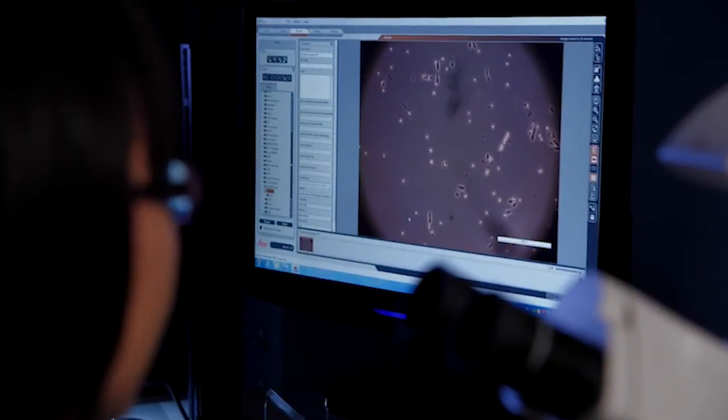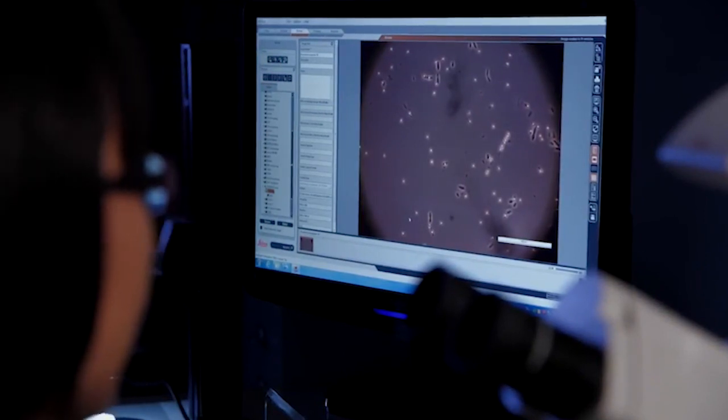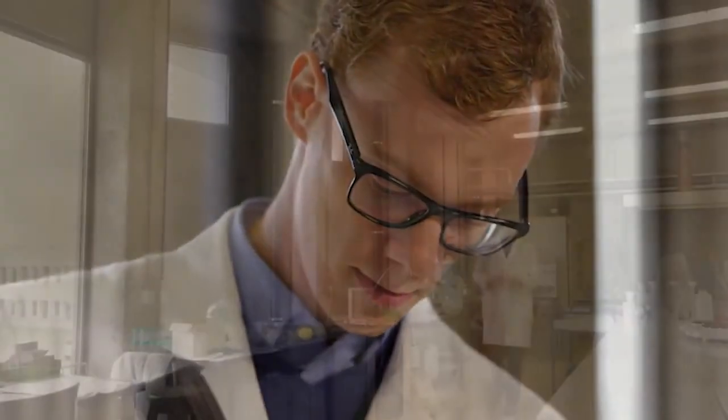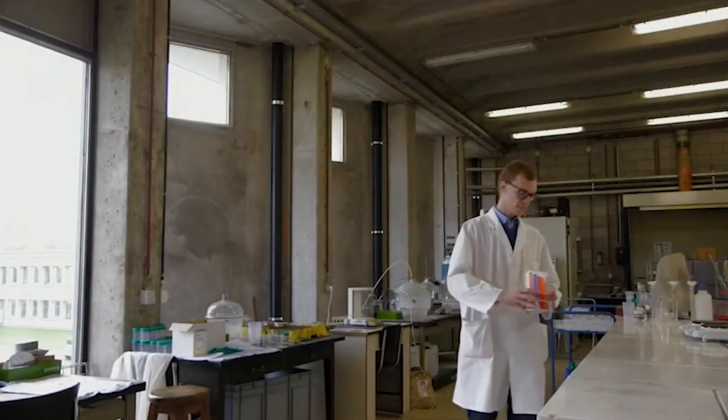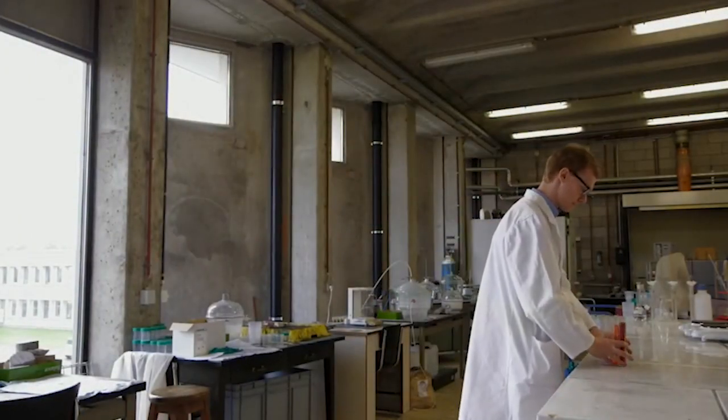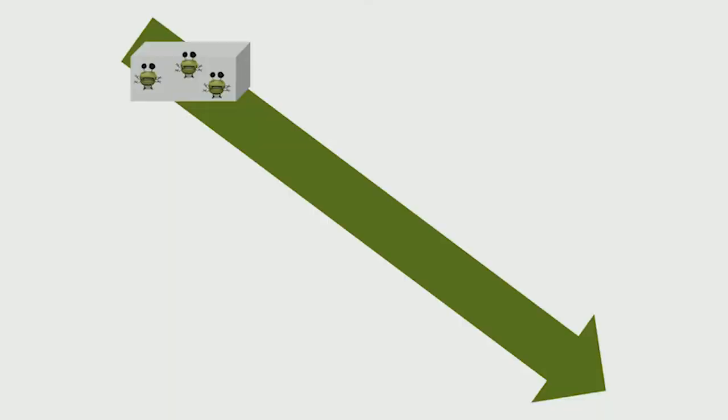These dormant bacteria become active as soon as they come into contact with nutrients and water, which intrude via the crack. However, these bacteria cannot directly be added to the concrete matrix, as they would be crushed in the small concrete pores during hardening. Dormant bacteria are embedded inside concrete.